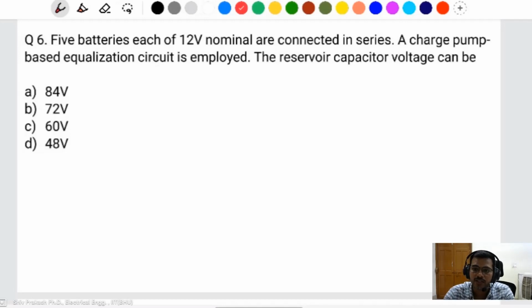Then it will charge the cells, then some of the cells are fully charged and some of cells are lesser charge, or some are not full charge, but some of the difference between them. Suppose the one cell is full charge, then you can't go on the charging. You should stop the charging because of the one cell is overheated, overcharging if you do not stop there.